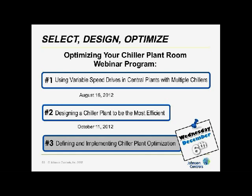We were keeping it constant. And the third column was when we lowered the flow down to the 80%. So all of the equipment in there had variable speed drives on it. It was really just a question of whether you ran them as variable speed drives. Variable speed drives can replace the functionality of a balancing valve and at least keep one of them open so that you don't waste head in the entire system forever through a balancing valve. And they're cheap enough now that it's worth it.